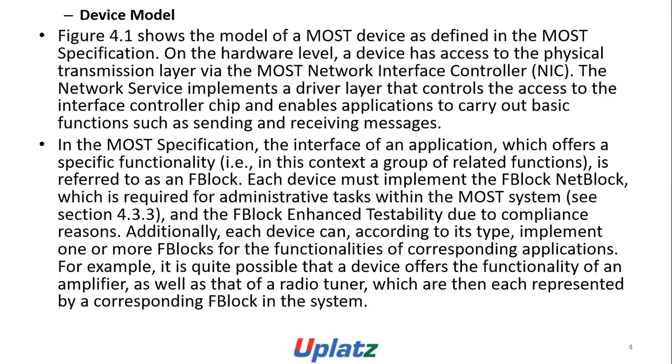In the MOST specification, the interface of an application which offers a specific functionality that is in the context of a group of related functions is referred to as an FBlock. Each device must implement the FBlock NetBlock, which is required for administrative tasks within the MOST system, and which enhances testability due to compliance reasons. Additionally, each device can, according to its type, implement one or more FBlocks for the functionalities of corresponding applications.